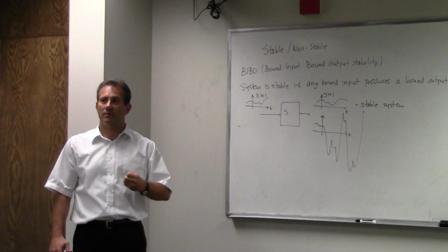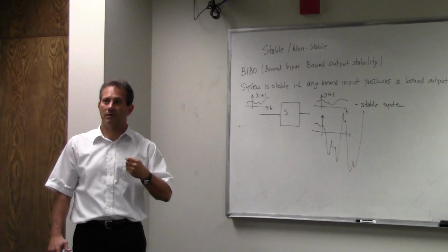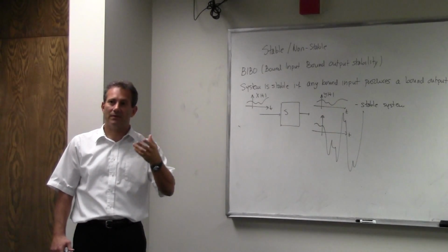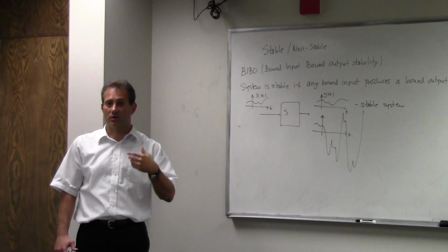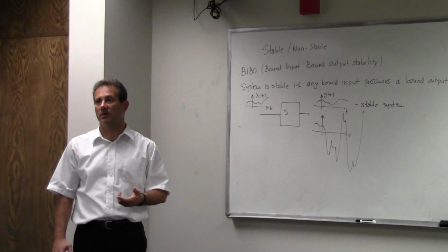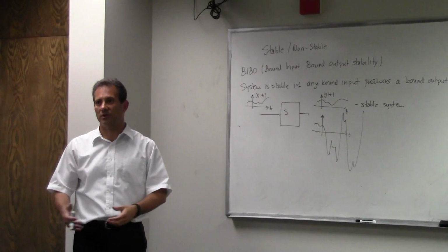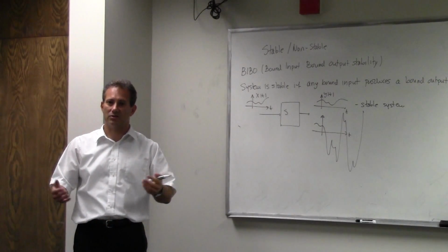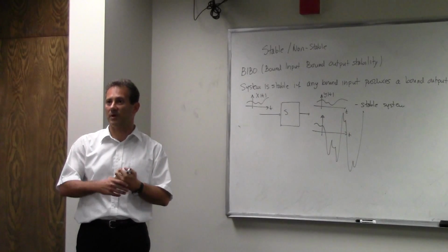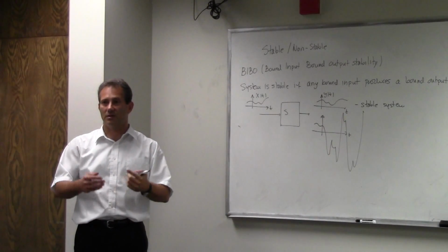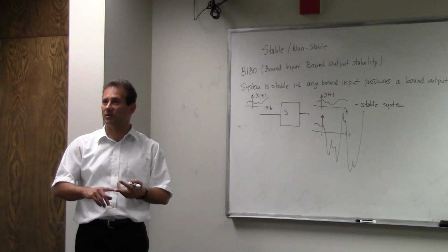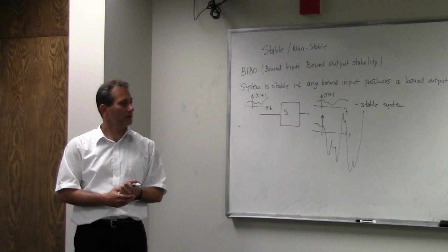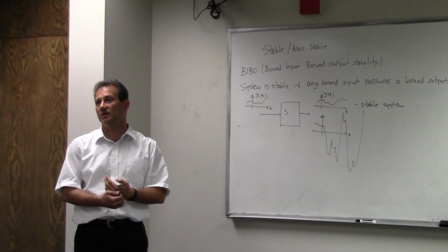How about if I have a buffer in front of the signals before it oscillates? It will reduce the oscillation. Well, then if you have an amplifier, right, then oscillations are highly undesirable. And there's a whole set of tools that you have at your disposal to reduce oscillations. First, you have to do the analysis to see why this particular circuit oscillates. Is it the positive feedback? Is it the placement of the poles, zeros, where they are? And then depending on what the causes are, you have a whole bunch of stabilizing procedures.